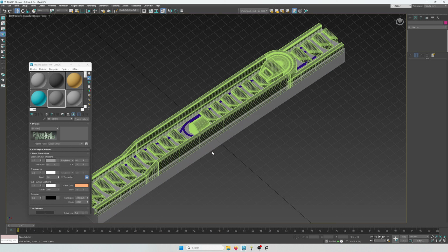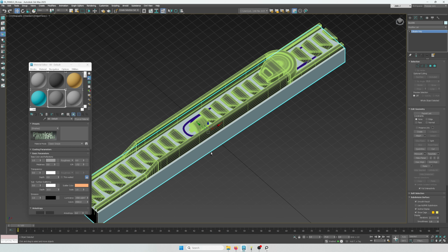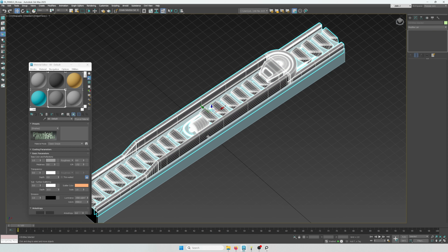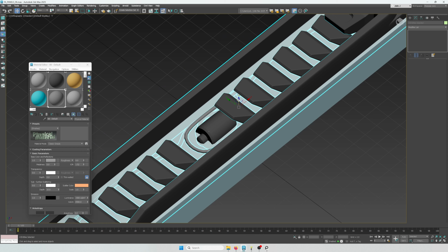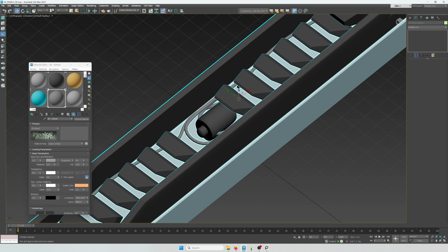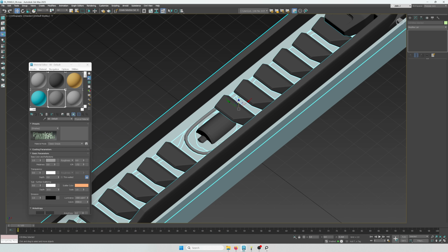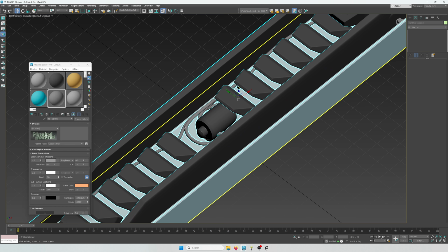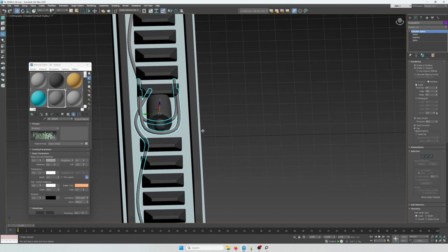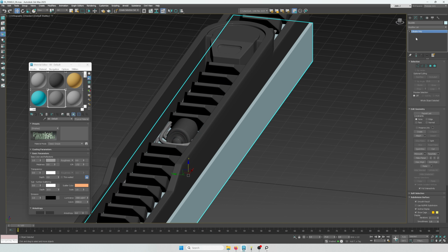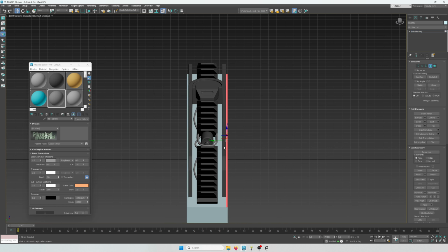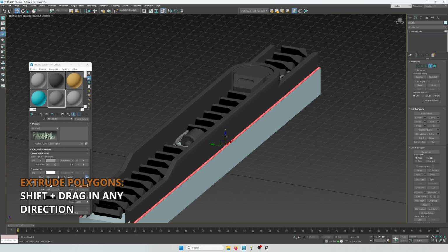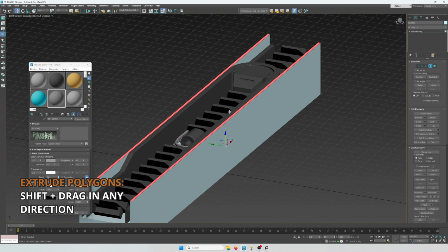Right now, I'm trying to determine the distance of the lowest part of the model with the highest part. And this has a very big impact on the texture. It impacts the AO and the height map. And the AO impacts everything else. Some examples are the dirt and the edge wear. So I don't want the distances to be too drastic nor too shallow.